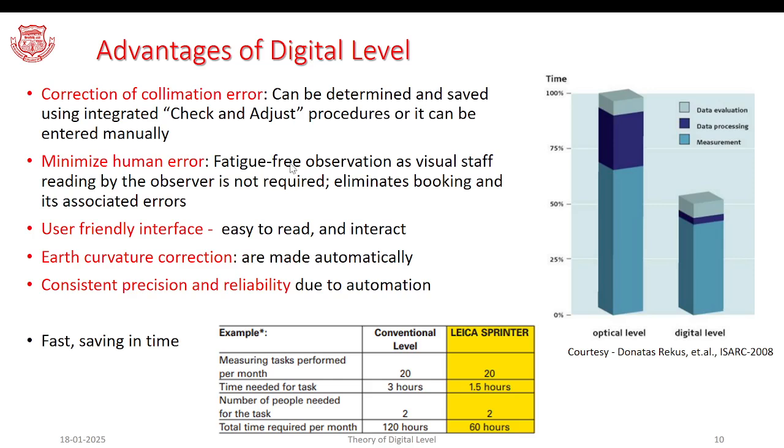We need not have the optical means to measure the readings manually, but here the readings are read automatically and booked, worked out with the reduced levels. So there is no need to maintain the field book. If one is in need of confirmation, one can have certain keynotes, but it is not an essentiality.